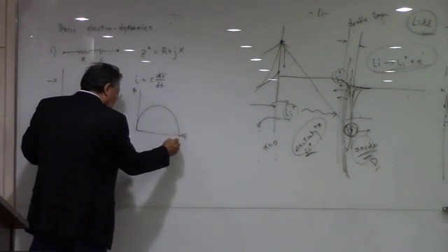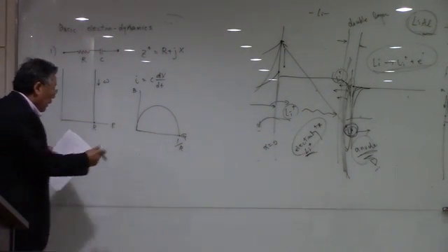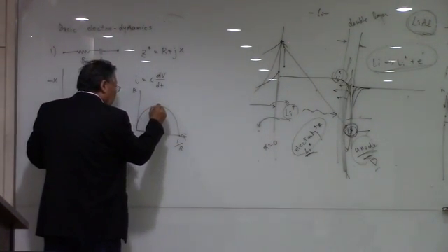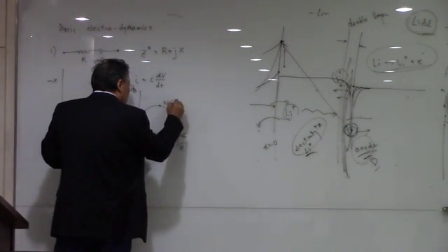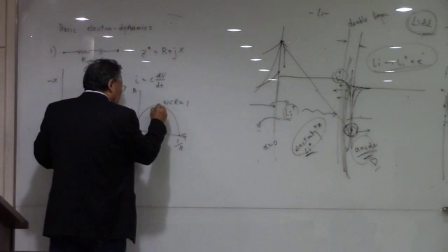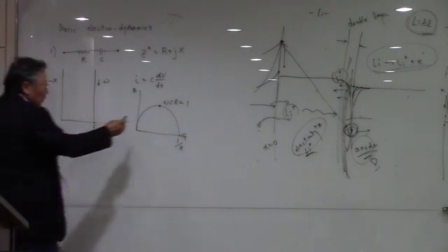And at this point, this is R, 1 over R. And then we're going to have information about the capacitance here, because at the maximum point here, the product of the frequency W, the capacitance and the resistance is going to be 1.